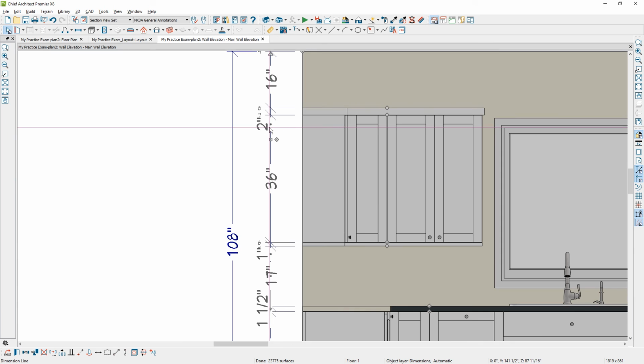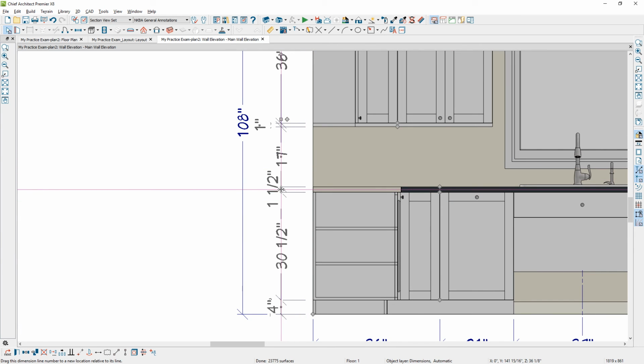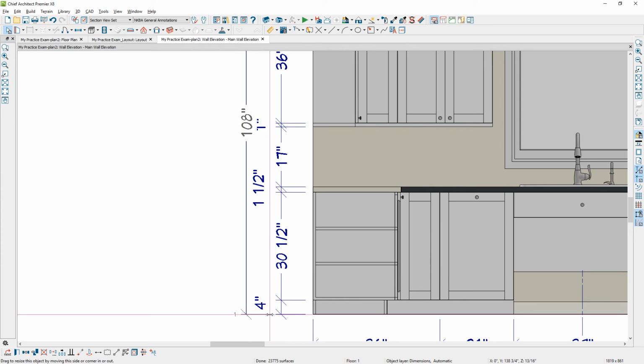Slide it in, and again, if you zoom in, you can get the 4-plex move handle. If you want to move these above the dimension line, maybe pick one and go with it so your style is always the same. And I'm just going to pull this one out as well. You can use your crosshairs here to line it up, make sure that it's well lined. Pull this in a little bit, and then I'm going to highlight the extension lines, pull those over.